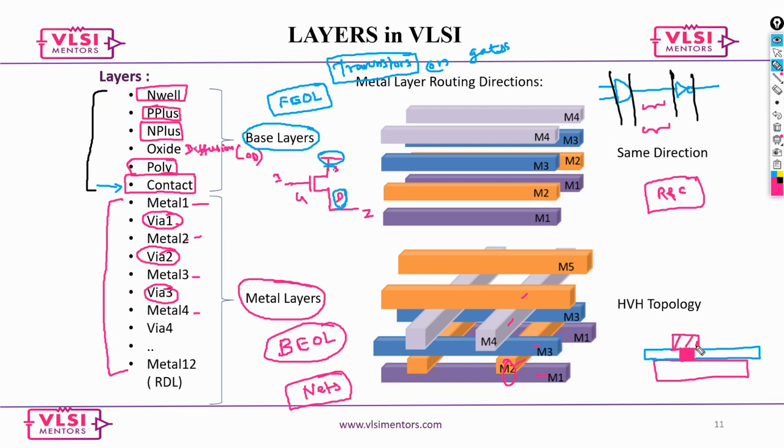So this layer M1 and this M2 are connected. So it is basically metal, then some dielectric, and then again a metal. Now you etch it and then do a metallization, which would connect this M2 and M1. You will get a good understanding of this when we get into the layout portion in the tools.